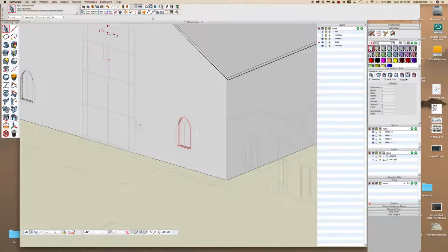So if you remember, we can take and we can subtract two objects, one from each other, and get the opening. So all we need to do is create something that we can use here to subtract, move it into position and subtract it on this wall. So let's go ahead, and this tool down here, which is a new tool for you, is a derive, and you can derive objects from planes and surfaces, etc., that you've got in the model. So this is a handy tool.